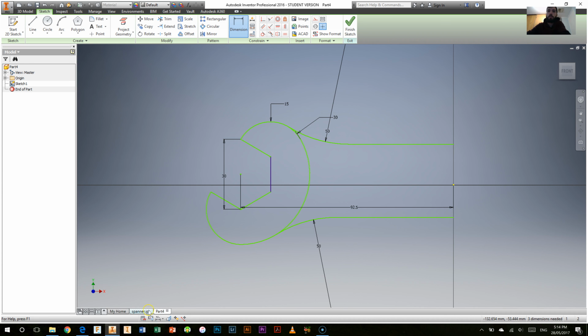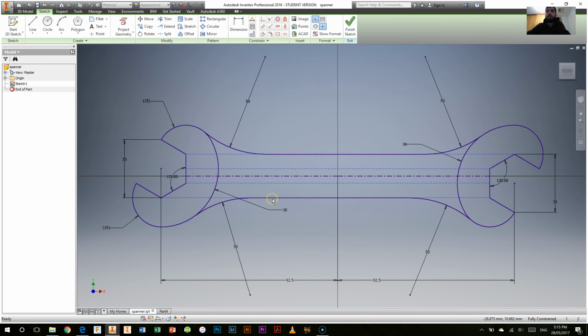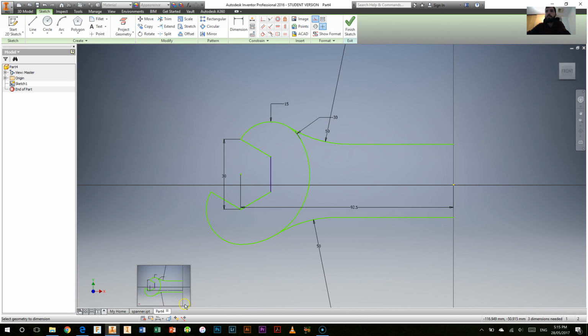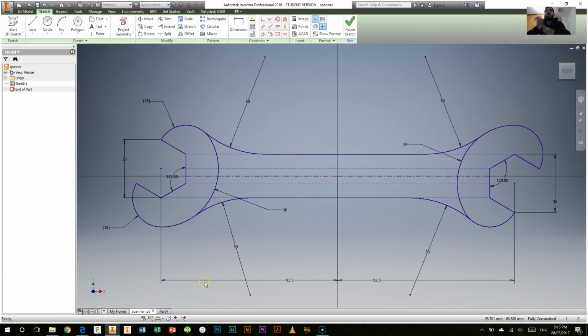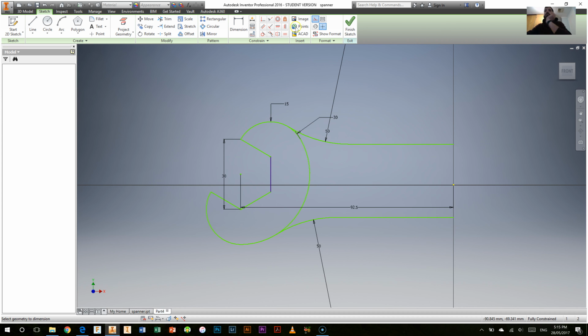It doesn't quite look like the sketch yet. You can see this one looks a little bit skinnier in this area. So we'll have to fix that up as well. Now to do that, if we have a look at this sketch here, you can see that these lines actually line up with this construction line I've added in. And that construction line lines up with this vertice of the hexagon. And in the case of the bottom line, it's very similar to that line there to the bottom vertice there. So we can add in a constraint to help us with that.